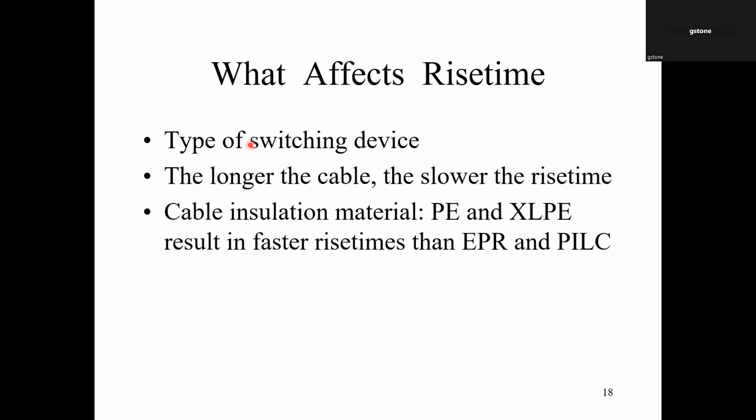This is basically because of the insulation shield and conductor shield on the cables, which absorb energy, especially at high frequencies, and therefore the high frequency components are more strongly attenuated than the low frequency components. And this effectively lengthens the rise time, and that makes this surge more benign to the machine.